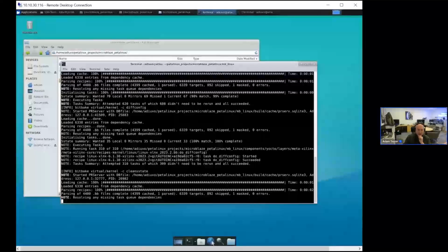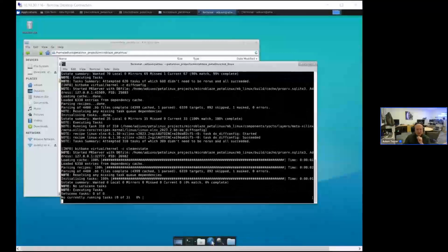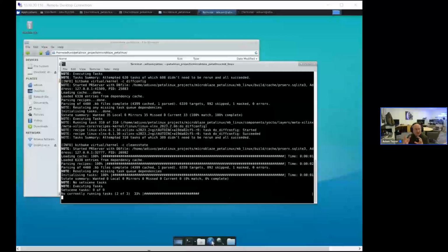So there are some good points coming up about looking at the other Vivado IP. It will generally pick up other IP, so if you put in any AXI related stuff, DMAs, it will generally pick it up, and then you can work with it using UIO.